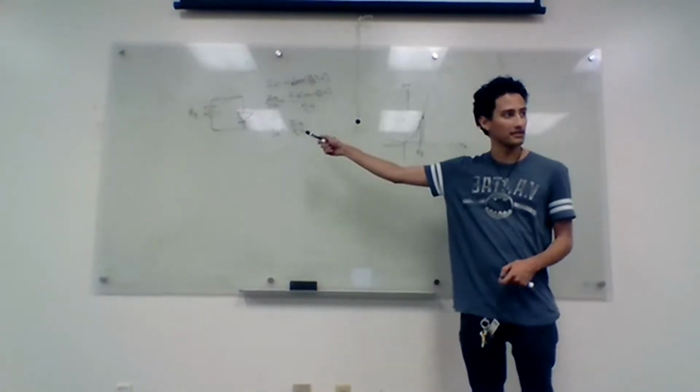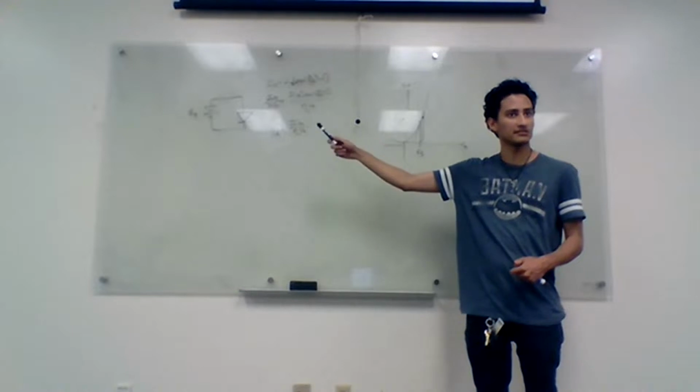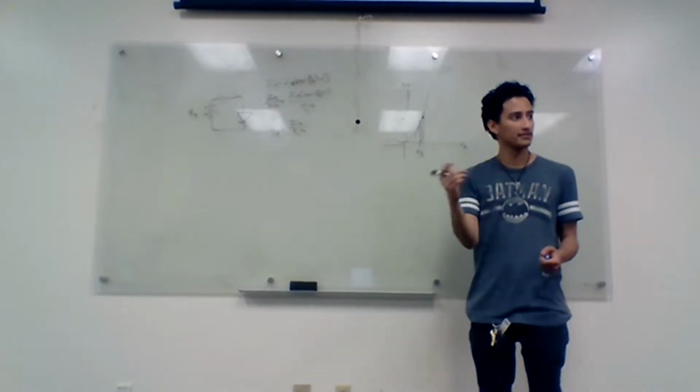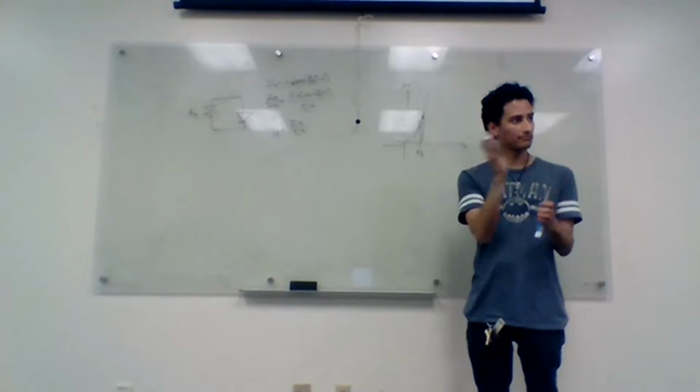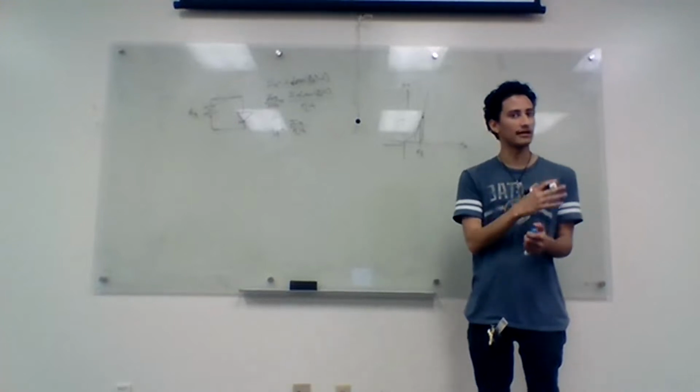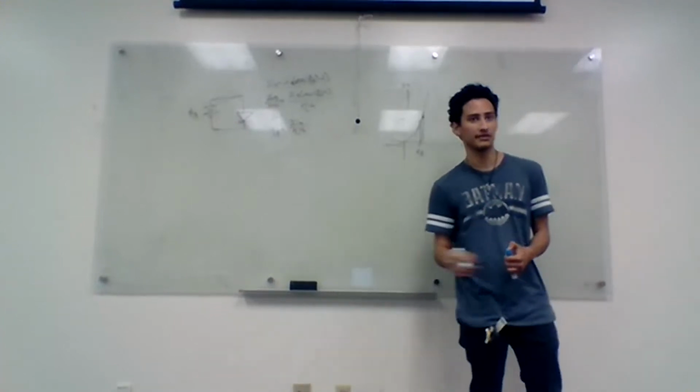That ties into what we were just saying here. Those test conditions, if they tell you IS, they got IS by reverse biasing it a lot, and that value is just what they're using there. And that is what you can use for IS. VAF doesn't usually give you what your circuit is biased at.